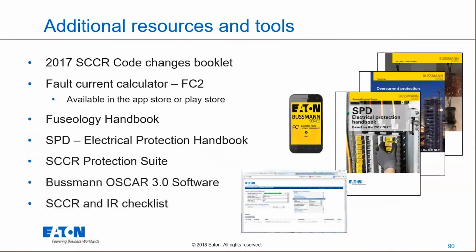So here's a question, Matt. Someone's asking, how about field changes at the control panel? For example, adding extra inputs to a PLC or an extra motor starter. An extra motor starter will be a problem, because now it's part of the control circuit that has to be reevaluated, but extra inputs to a PLC is part of the control circuit, so that won't be a problem. So if it's part of the power circuit, it'll have to be reevaluated again.